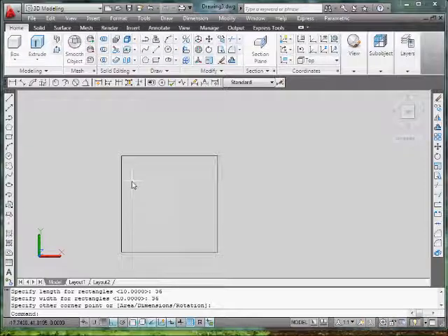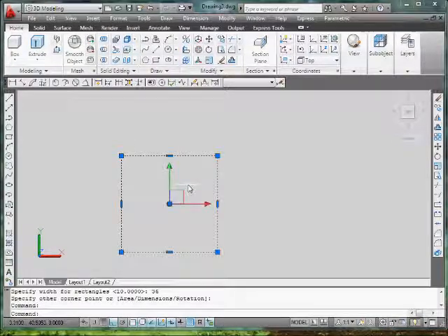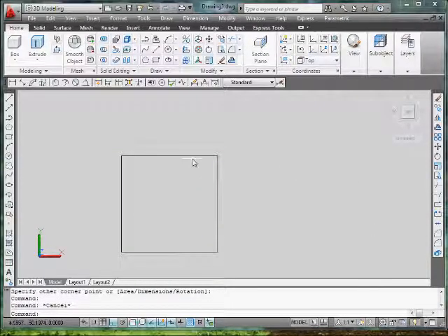We have this. It's one polyline because it's a rectangle command. So it comes as one single combined line, which is fine for the moment, but we're probably going to explode it later, so we can make that door. But since we have the wall exterior and we have it in one polyline, what I recommend is we do this offset command.